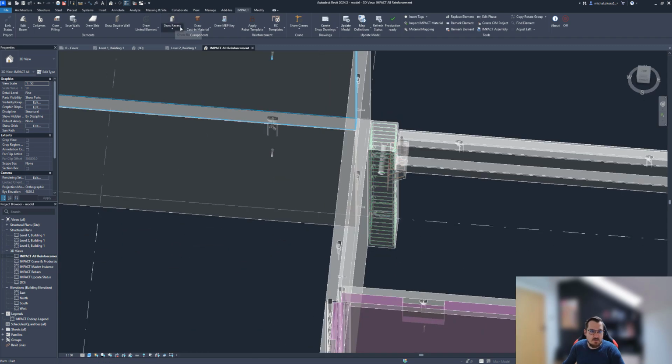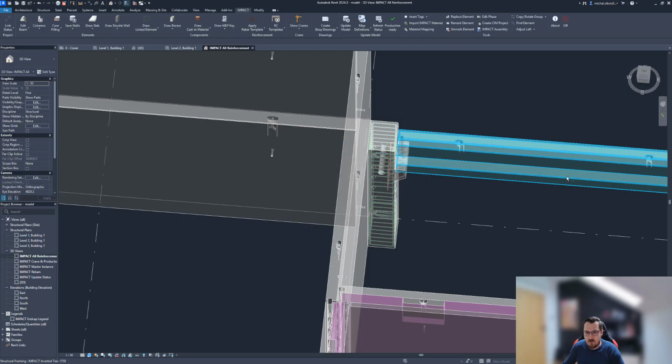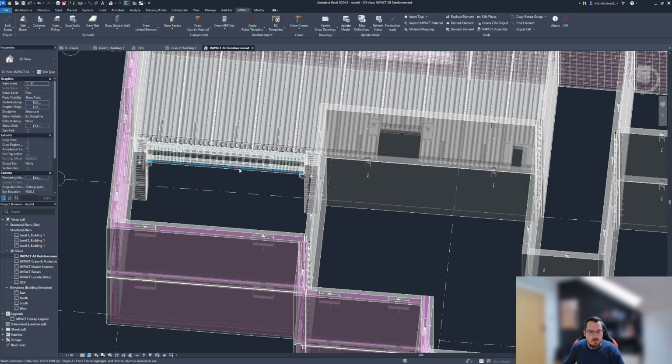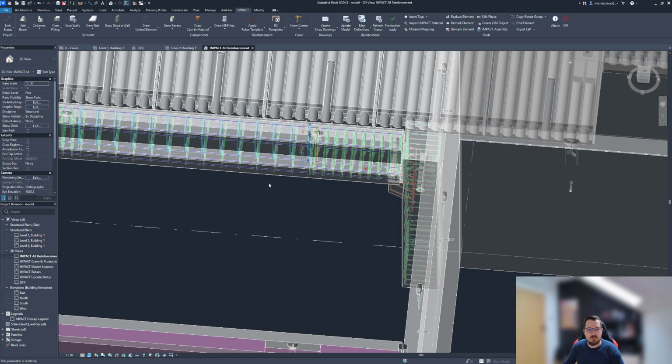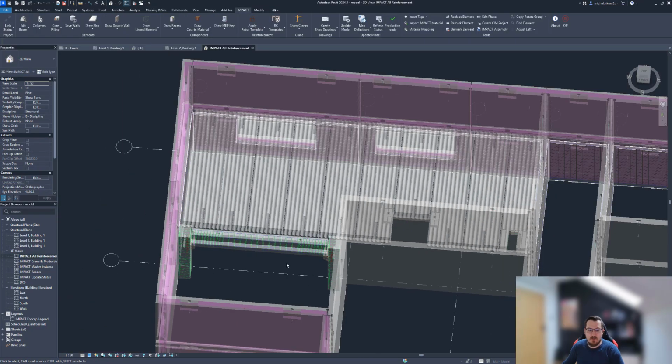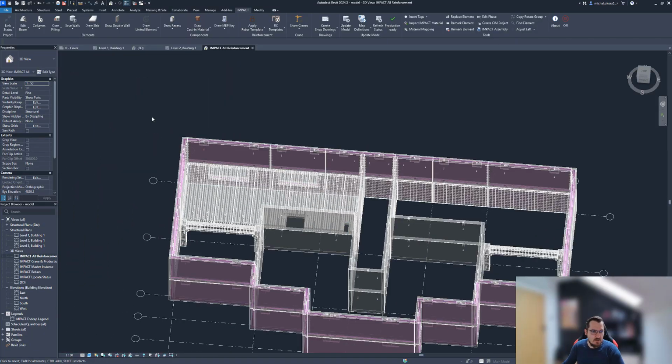And let's add the last rebar templates really. For that, let's go beam reinforcement for our inverted T beam, like so. Then you can of course edit that reinforcement. You can edit some parameters, you can edit the spacings. So that's a lot of setup that you can do that will automate your work later on.